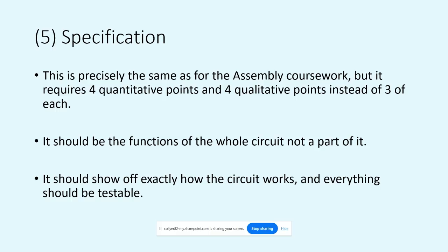when the on button is triggered, the red LED flashes for 30 seconds. In fact, that's really 2 points. So when the button is pressed, the LED starts to flash. Point 2, the LED flashes for 30 seconds, plus or minus 3 seconds. Notice I state the tolerance to ensure that it's got the attention of the user. I've explained why I picked the numerical value, so do make sure that you explain it. Everything should be testable. Everything should be what you're going to test in the realization later on.